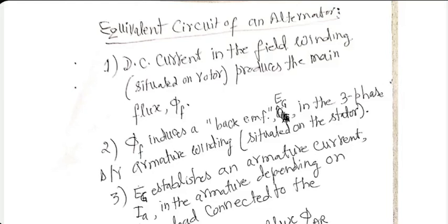What happens in an AC generator or alternator, if you want? The rotor has poles. They need to be fed using DC current. Rotor rotates, the poles produce a rotating flux, which cuts the static winding on the stator and produces the voltage.